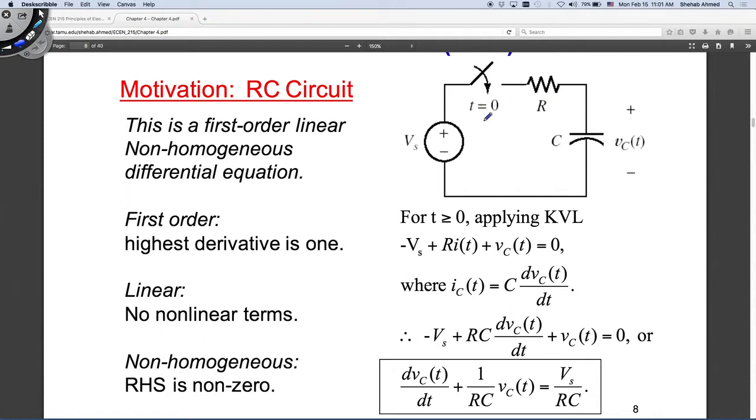Right, so we define the polarity, the direction of current flowing this way. So I can put a positive here and negative here for the capacitor. They've defined that for you, which means also that the current is flowing this way in the resistor, so I put positive here and negative here. Right? So now apply Kirchhoff voltage law. Anytime you see an element, take it into consideration, including the capacitor. So the sum of voltages around the loop will be 0.